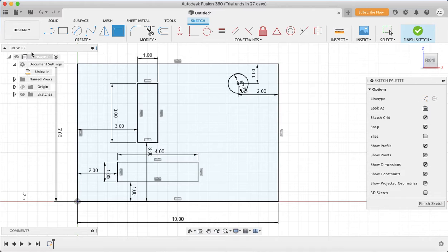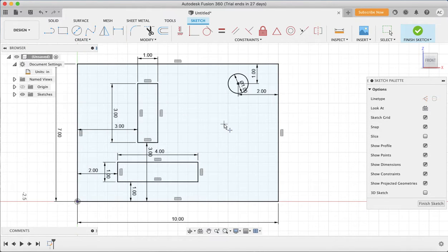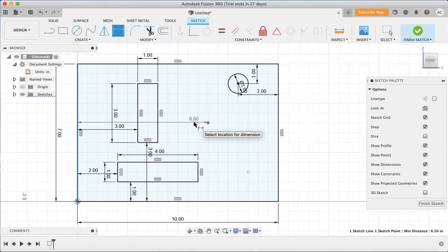The line connects 2 points, so I need to mark those points. And if you find a better way to mark points on here, I would love to hear it, because I am not. What I have found so far is I need to dimension each of the points. So this first point will be dimensioned from the origin, so we want it to go over 6.25. So I'll click on the line, click on the point. I want this to be 6.25, and then I want it up 4. So from the point to the bottom, I want that to be 4.